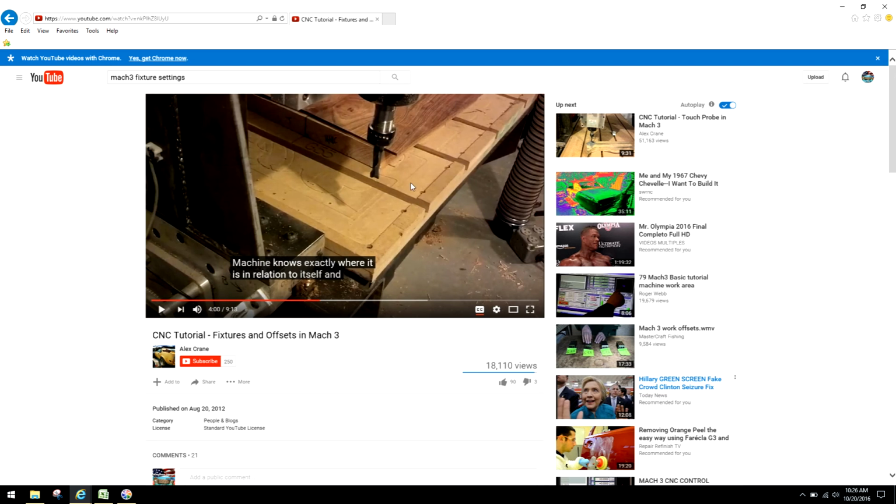Okay, so once again, what we need to define here is what your true objective is when you're homing your equipment. When we speak of homing, there's that miscalculation again of saying, okay, do I know where my machine exactly is relative to the table? Do I know where the spindle is relative to the table? Are you going to be machining in the bottom left corner of the table when you're facing it, looking at it from the rear? Or do you want it to where you actually speak of the home position where we're actually talking about the material at hand?